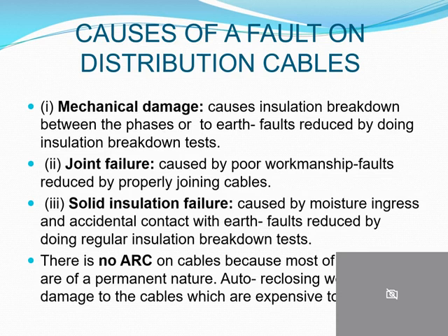So an auto-reclose will automatically close after a certain period of time that we set it to close at. And if nothing happens when it closes, in other words, that fault is no longer there in the system, then it remains closed. But if that fault is of a permanent nature and it is still there in the system, then it will open again automatically.